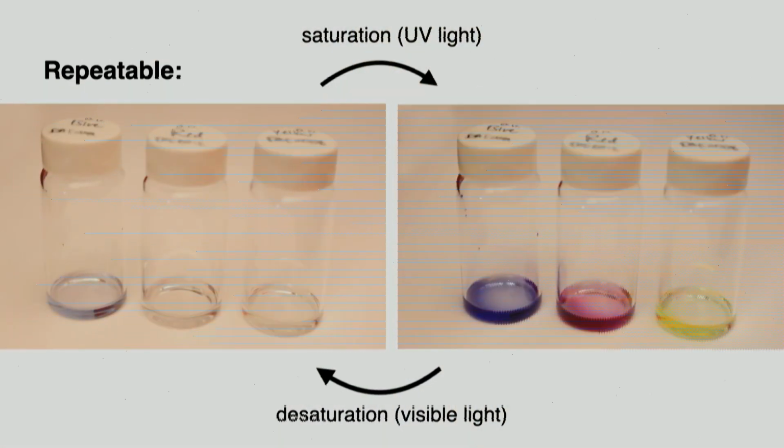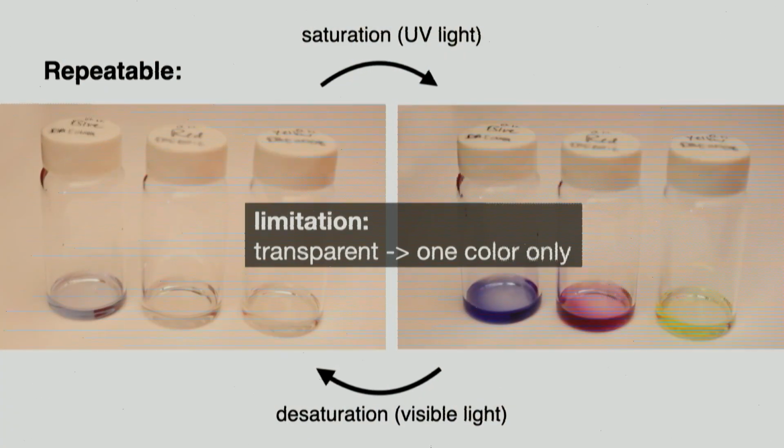So these photochromic dyes, you can actually just buy them. We buy them from a company in Japan, but the limitation here is that normally they are only a single color. You can buy something that is transparent to cyan, transparent to magenta, or transparent to yellow. But if you just sprayed one of those onto an object and then shined some light, you would only get different levels of, let's say, cyan or different levels of magenta, but not a multicolor texture. So our big contribution here is figuring out how we can actually do a multicolor texture with different colors in it.